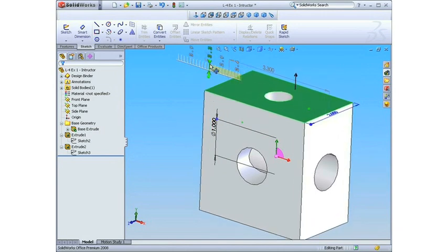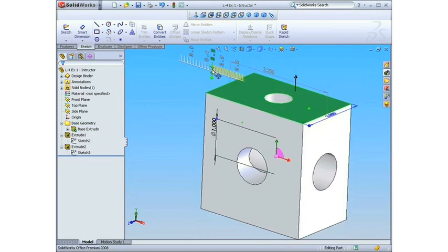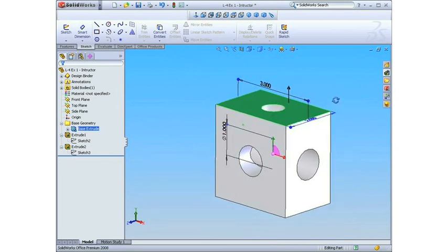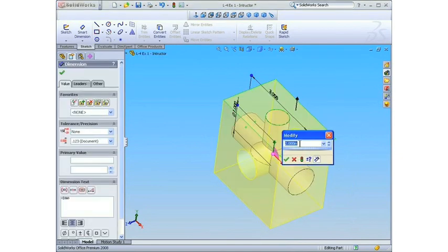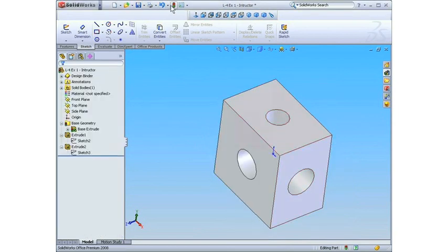I'm going to just go ahead and drag this to 3 inches, so I'll snap along my ruler. Oh, I've gone too far here. Go back a little bit. There we go, I'm at 3 inches. Then I'm going to modify this dimension to 3 inches as well. However, when I modify this dimension, I'm going to simply double click it, and we'll see that we also get that ability to change it, except in this case we can enter in an exact dimension.